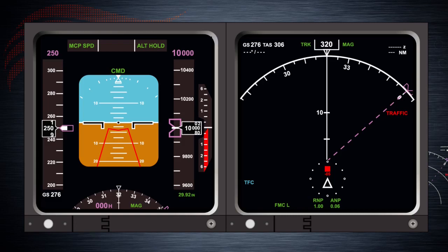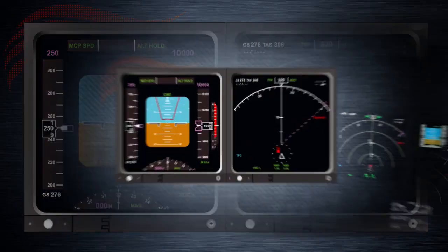"Climb. Climb." This resolution advisory requires that the pilot climb to avoid the pitch regions displayed on the PFD. In this case, the clear, safe region will be towards the top of the attitude indicator, prompting the pilot to pitch up. Don't forget that TCAS is expecting you to respond within 5 seconds and achieve a load factor of at least 1.25 G in the pitch up to climb. The autopilot must be disconnected for this type of resolution advisory.